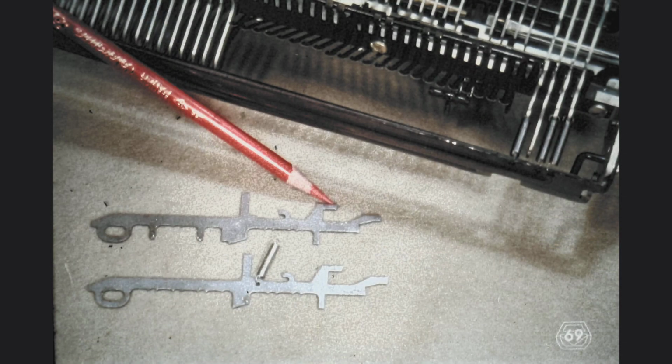Finally, we have a chance to examine an interposer in our hand. Notice that they are numbered. The indicated lug positions itself between the steel balls of the compensator tube when the interposer is depressed and latched down. The underscore-hyphen interposer in the foreground, with a spring still on it, has only one lug pointing downward beside the wide center lug. It turns out that this lug is the one not used on American keyboards, so it doesn't matter whether it's there or not.